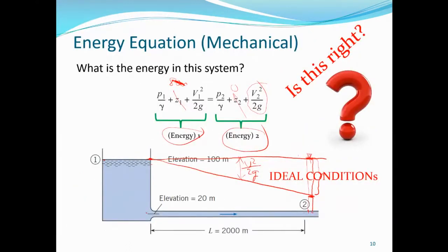So because of the head loss here, you realize that here you have the velocity head, and then you have the head loss here, HL, and this is now the velocity head. So when you put a piezometer here, water will rise up to the level of the piezometric pressure head, which is to this level.